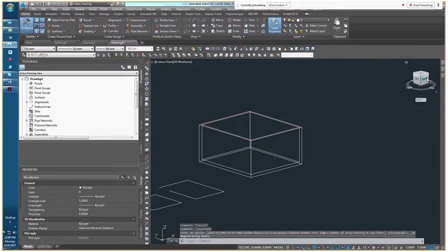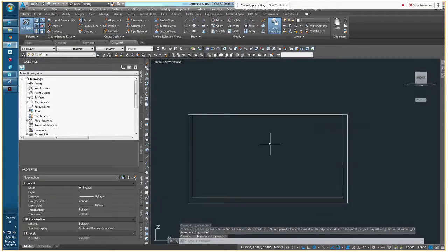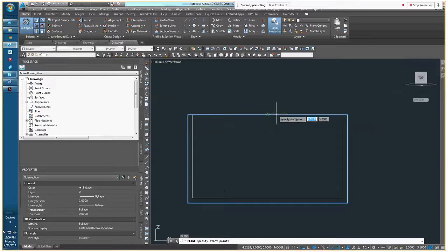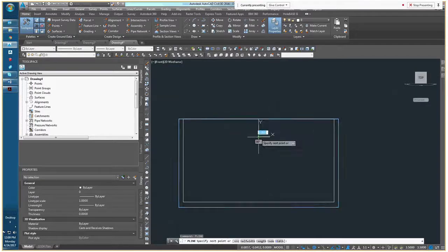The last thing I'm going to do to create the V-notch weir detail is to create a V. So I'm going to draw myself a little guideline here, and again, I'm in an elevation view, so to speak, of this. And again, I'm going to use my polar commands, polar snapping, to snap to a 45-degree angle, and then use tracking to snap to both the top and to a 45-degree angle.